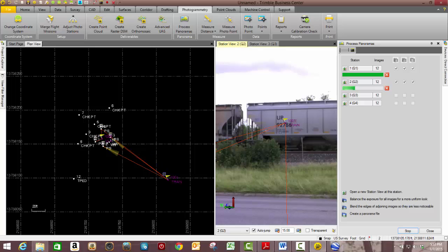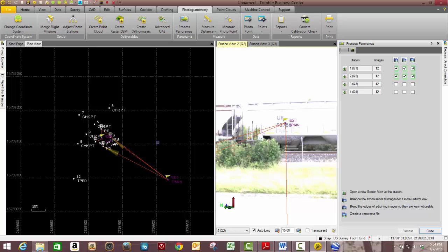While this is cranking out, just kind of going over it again, we imported in the job XML file. It came right in. The photos automatically are imported into the job XML as long as they're on the same directory of your computer. We performed an automatic fully constrained adjustment, which, as I mentioned, I had 4 photo stations. It took probably about 3 minutes on my computer, but it might take up to 5 or 6 minutes with a slower processor. We reviewed the results, pulled up the network adjustment report, and then we went straight into measuring photo stations and covered how to look at the quality of the photo stations that are created. And again, that depends greatly on the geometry and the spacing of the photo stations we collected these images from. We also looked at the point derivation report as another way to check the quality of the points that are created. So with that being said, now I can see that my photo files were successfully created.